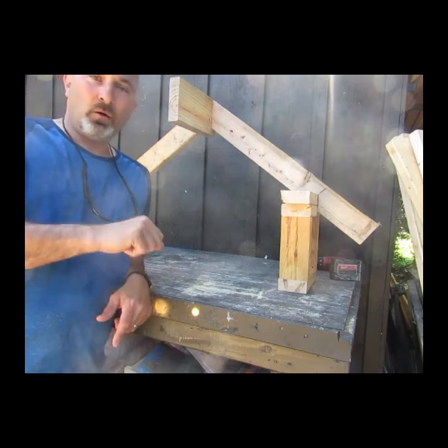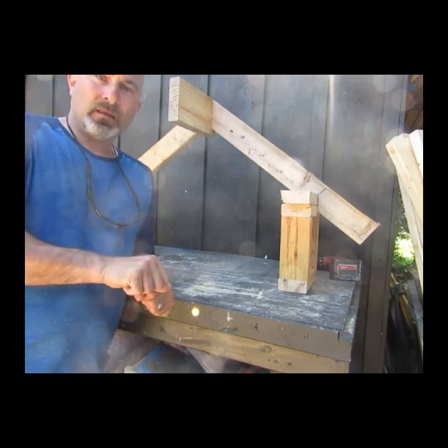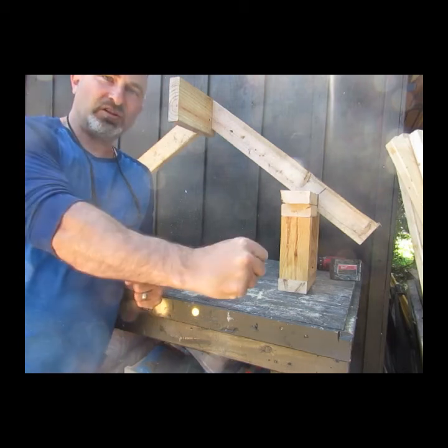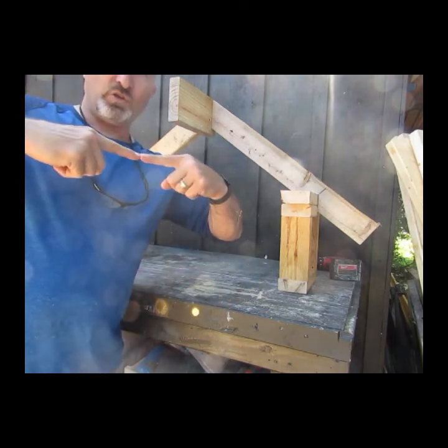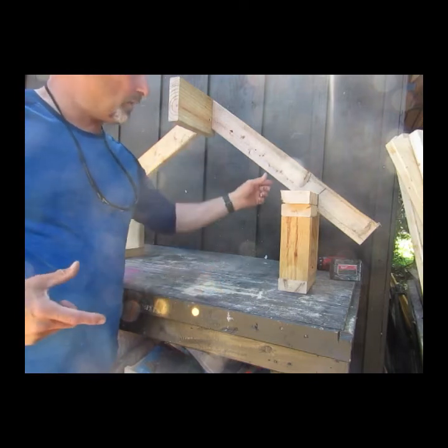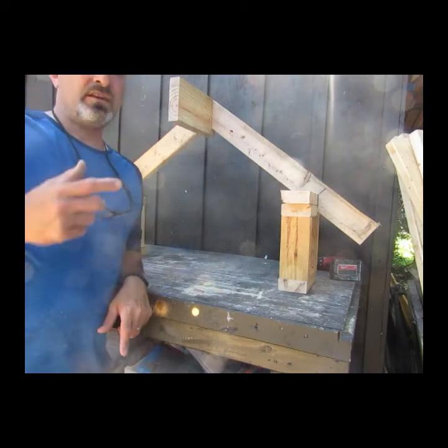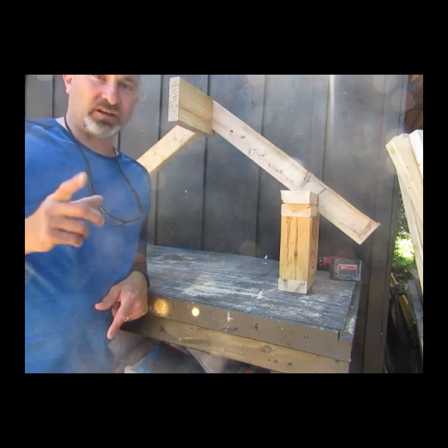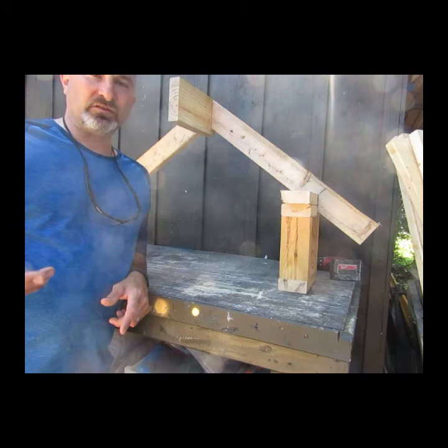So the nail holds the wood from sliding back and forth. The most you want that nail to do is resist shearing apart. If you've got a nail, you don't want it to have so much force that it snaps the nail, allowing the wood to shift back and forth. So the nail is a placeholder. The wood is what resists the pushing and the pulling. So you can put as many nails as you want in.